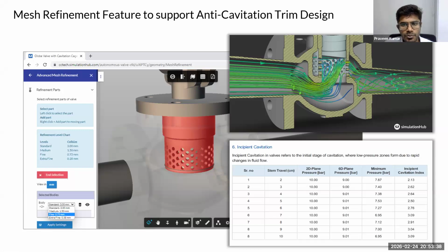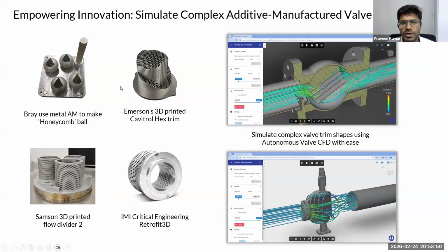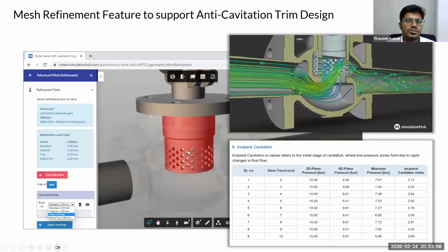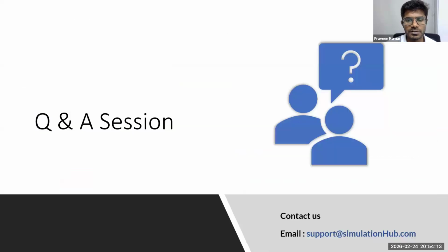In the expert mode, more options and controls are given to the expert user. You have control over mesh refinements, turbulence model, and whatnot. So you can model complex geometries as well using these options. Let's say you have your own SOPs for your team, where you follow a certain turbulence model and numerical schemes. That control we can open. So if you have the expert mode open, then you can control those as well.